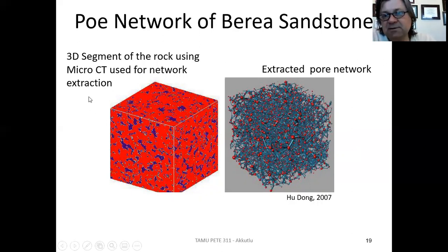Micro-CT means that it's very much like an X-ray machine, like you go to the doctor to get your X-ray because you broke your hand, right? So basically, to find out where the crack is, they take an X-ray image of your hand, right? Here you have the same technology, but rather than targeting whether your hand is fractured or not, it's targeting the pore space in the system. If it's micro-CT, it's even much better in terms of its focus. It can go in and detect very small pores in the system.